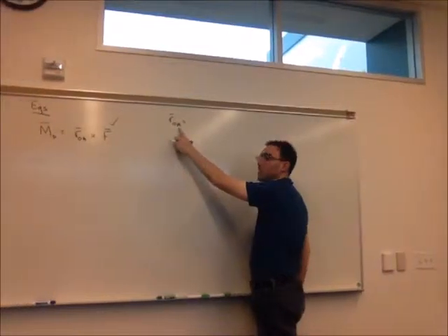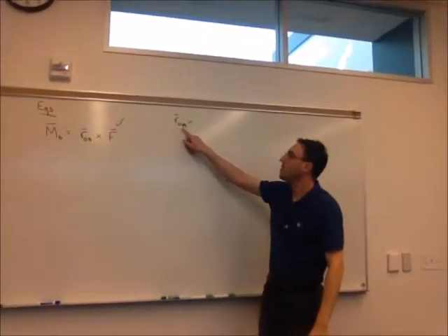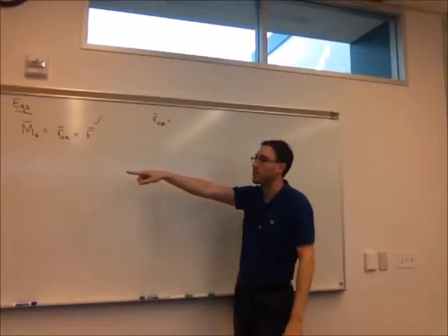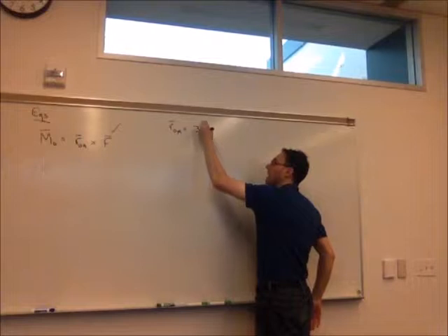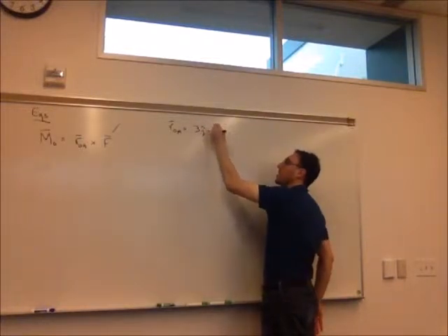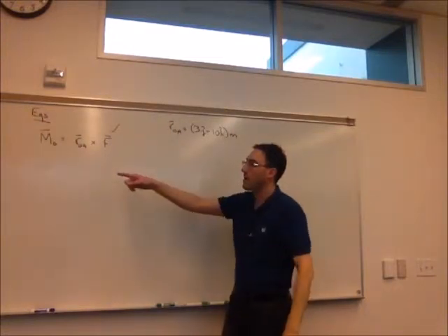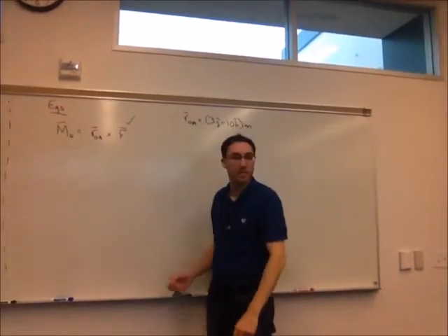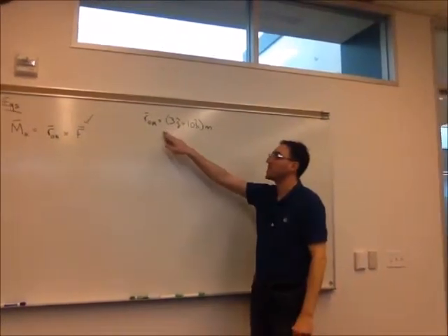Right, so it's the end point minus the start point. So remember, that's how we find position vectors. End point minus start point, so we can use the coordinates we have set up there. So 0I plus 3J plus 10K. So the coordinates of A minus the coordinates of O, which in this case is the origin, so it's 0, 0, 0. So that's ROA, it's a position vector.